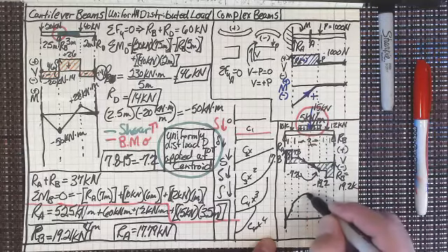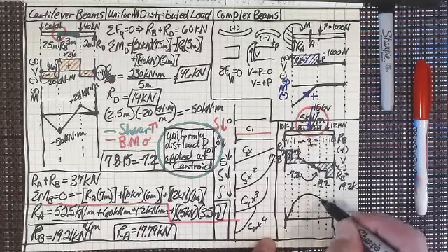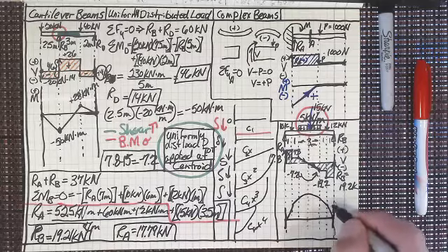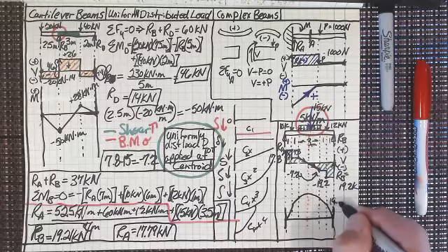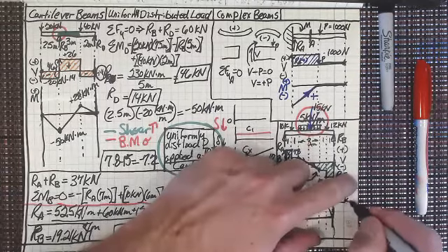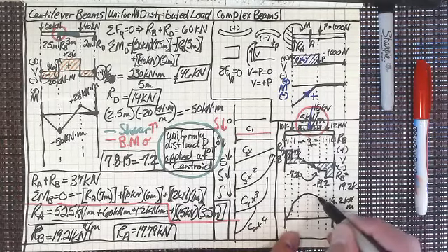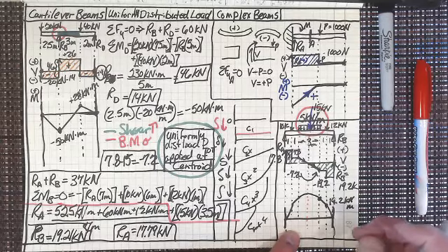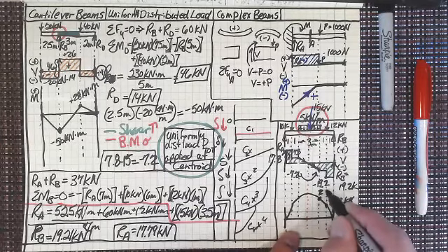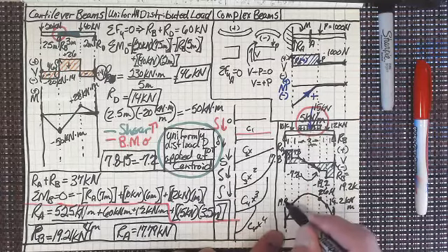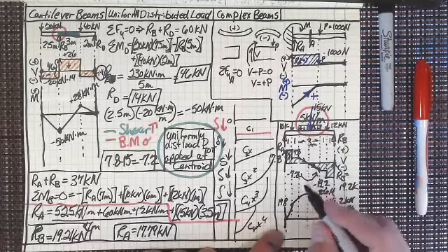So at that next point, we should be going like that. Then we go small, just like we did before, and then large. And we know that this right here is going to be at 19.2 kilonewton meters, right? Because that's one. And then that's 7.2 per meter. And so we can figure out what that is, because 19.2 plus 7.2 is 26.4, right? And then over here, this one went up to 17.8 times 1, right? Plus 7.8. 17.8 plus 7.8 is 25.6.